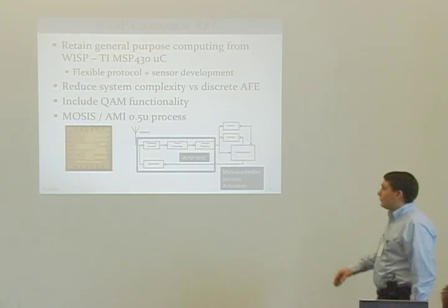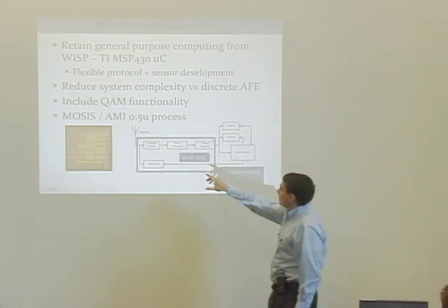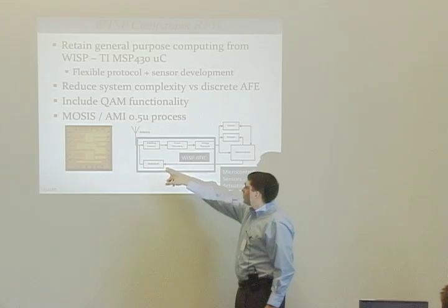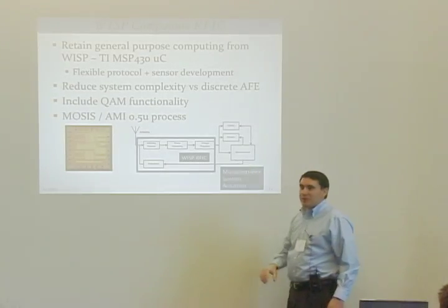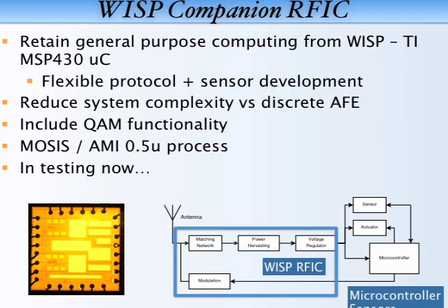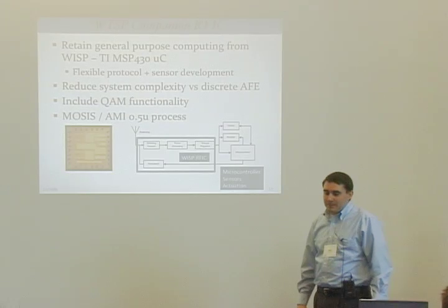At this point, we have integrated the matching, power harvesting, voltage regulator, and modulation components. The only thing remaining would be the microcontroller. We wanted to stay out of that business, because implementing logic or implementing a micro is something we would leave to Intel or TI, and just try to simplify the overall hardware as much as possible.